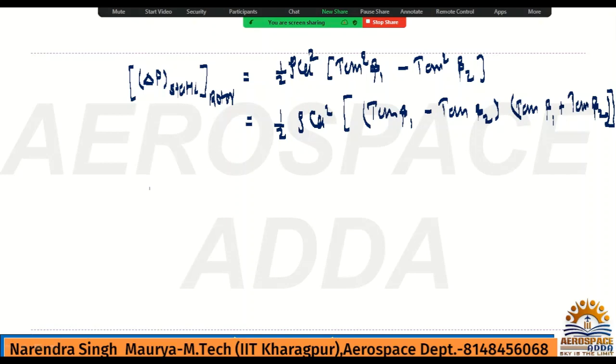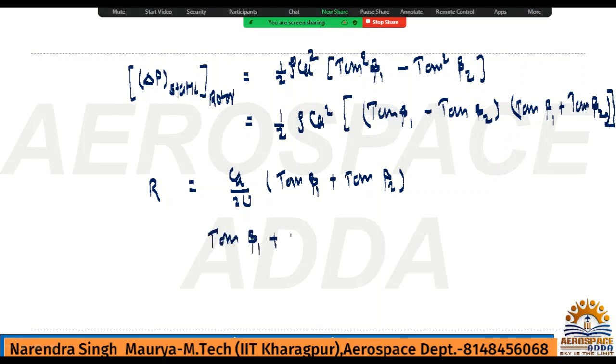So you know the degree of reaction. What is the degree of reaction? Ca by 2u, Ca by 2u, you got tan beta 1 plus tan beta 2. What I remember, it was Ca by 2u times tan beta 1 plus tan beta 2, that is the degree of reaction, right? Ca by 2u times tan beta 1 plus tan beta 2. What is the value of tan beta 1 plus tan beta 2? It is 2uR by Ca.